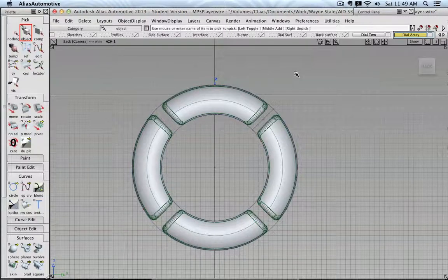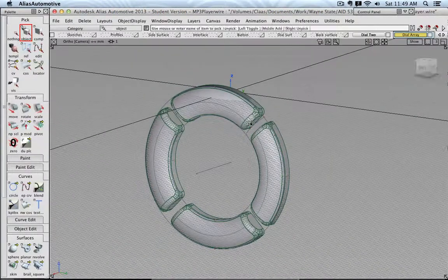And let me show you a different approach in addition to this one, where instead of defining a global geometry outline, I could now maybe select this arc and modify it, and it would update all four dials, because you see basically four different objects, but for Alias, they are all connected to each other. The top surface of each dial is actually part of one and the same surface. We just only visually cut out the space in between.